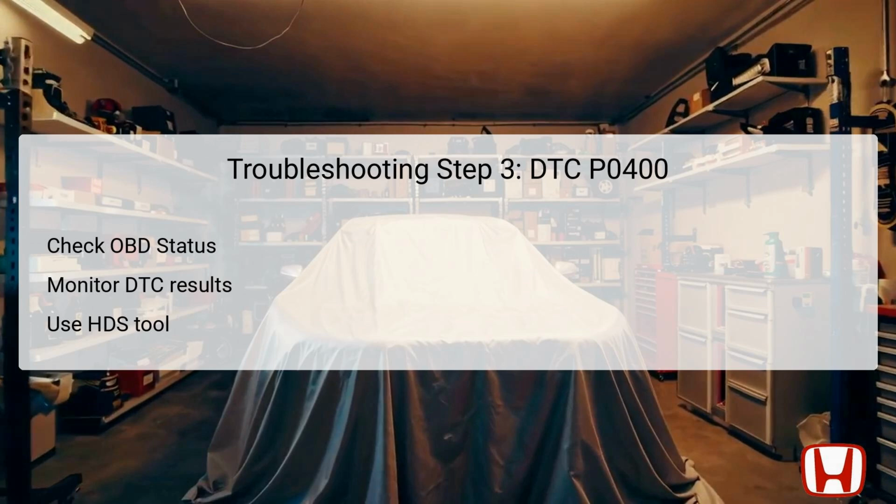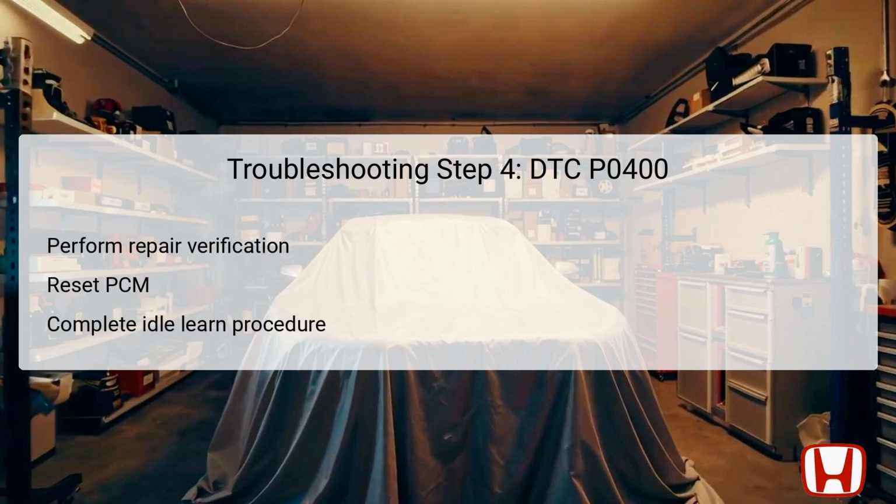functioning correctly. For repair verification, the first step is to initiate the vehicle by pressing the engine start-stop button to select the on mode, ensuring that all systems are operational. Following that, the powertrain control module, PCM, should be reset using the HDS tool, allowing the system to refresh any stored data and prepare for a new diagnostic evaluation.